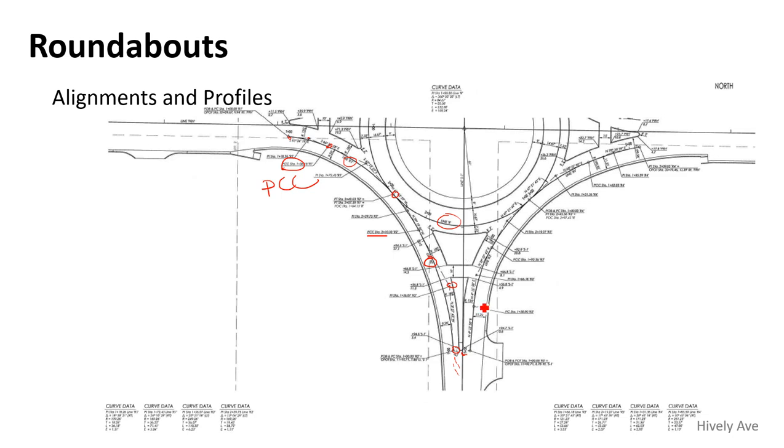So these are really complicated, right? We talked before about how to align roads. We rarely use compound curves. Well, in roundabouts, you use a lot of compound curves, right? This one actually starts on a tangent, and then we go into a curve, compound curve, another curve, and then we tie in tangent to the center roadway. So there's a lot of geometrics, a lot of stuff going on, but that makes a really smooth roundabout. That's how you ensure that it's built really well.